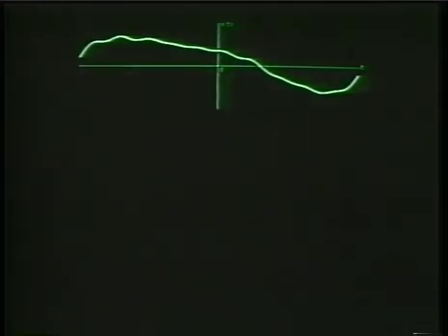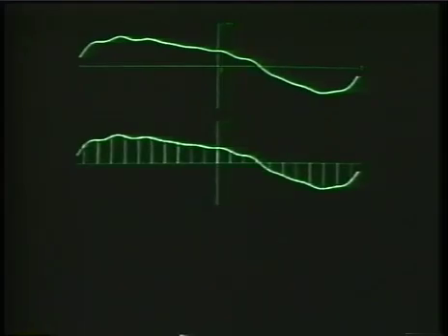So we have the same continuous time signal that we used previously with band-limited interpolation, and in this case now we want to sample and then interpolate first with a zero-order hold and then with a first-order hold. So the first step then is to sample the continuous time signal, and we show here the set of samples, once again superimposed on which we have the continuous time signal, which of course is exactly the same curve as we have in the top.